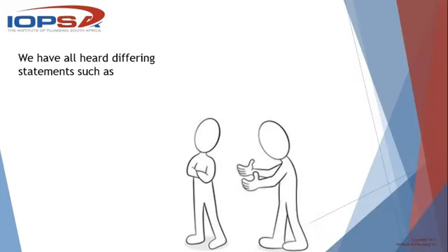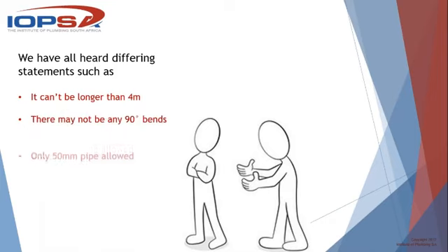I'm sure you'd agree, you can have three or four conversations in a day, one at a local supplier, one at a job site, and you'll hear differing opinions. For example, a drip tray overflow can't be longer than 4 meters, or there can't be 90-degree bends, you're only allowed 45-degree bends, because people read into conventional overflows and TP discharge pipes, and then transpose that onto drip trays.